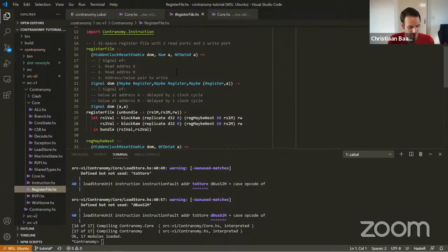I was hoping that you would say that this is much more efficient in terms of parts used, because the asynchronous RAMs that you have on the FPGA would definitely be more preferable, because that would fit into almost one, or perhaps two logic slices.